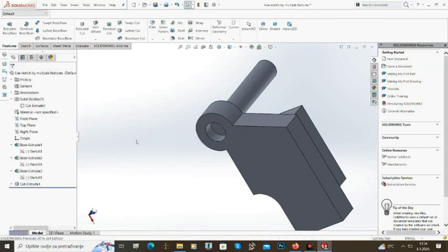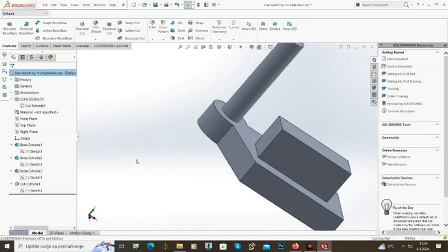And now here we have a cut. If we open the cut extrude, we can see this is the sketch 1, right? So now we use the same sketch by 4 features, okay? So this is also how you can save a lot of time when you have complex sketches, and you can save a lot of memory on your project.